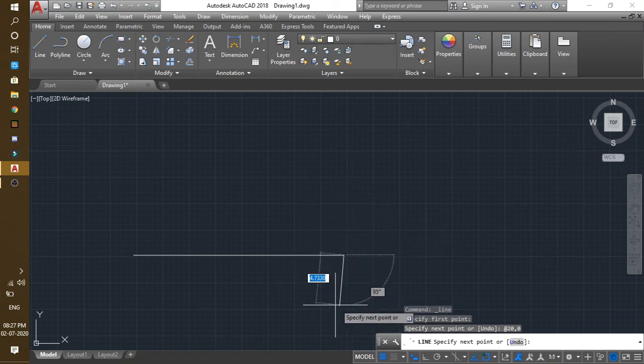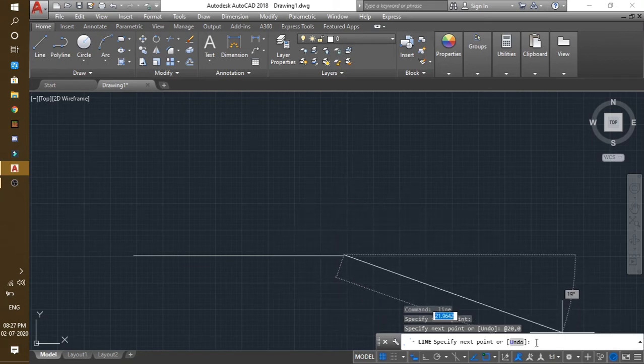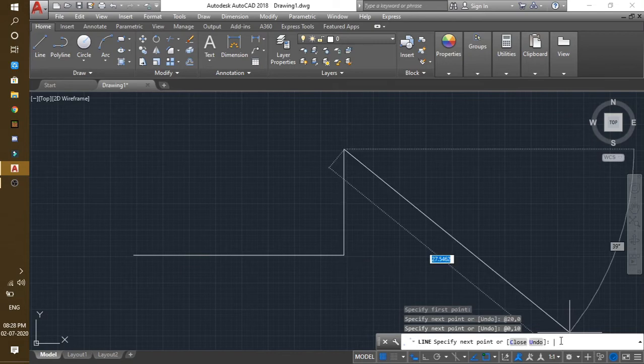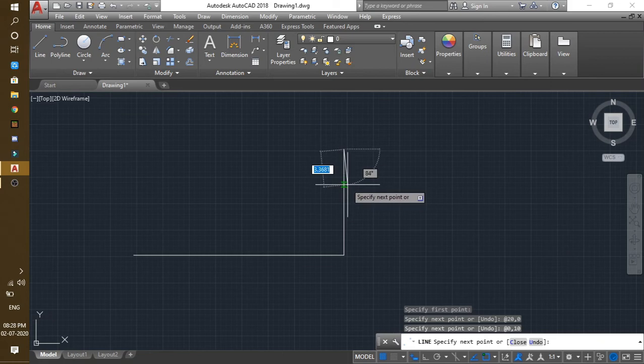Now since this is our origin, we have to change the coordinates a little bit. Just go over to the command box again and type in add. So this is your origin, okay? So since this is your origin, your x coordinate needs to be 0, because you are at origin. You don't need to go any further. So just put your x coordinate 0 and now put on the width of the rectangle you want, that is 10 in our case. I'll just put in 10 and after that press enter. As soon as you do that, a width of length 10 units will be formed.